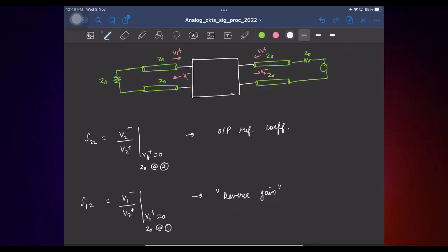Good. So the bottom line is this. In theory, although these y, z parameters are all nice, there are severe practical limitations in actually measuring them, right? A couple of them are the fact that you can't ensure a proper short circuit or open circuit at all frequencies, and because of multiple resonances, there is a high chance for things to become unstable. So that's what led people to invent a new set of parameters, which is S parameters. It is not like people invented something new to make you study more and to ask more questions. There is actually a reason behind doing this.